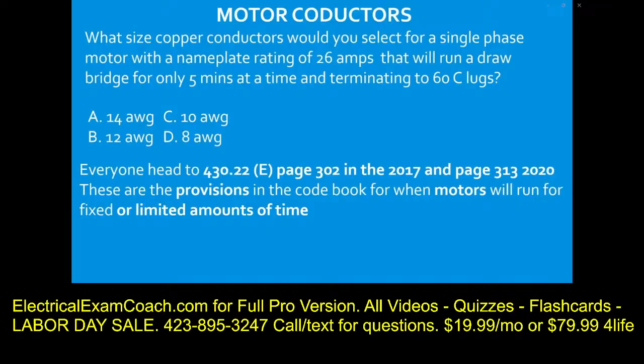Okay, so now we are going to go to Table 430.22(E). It's usually on the next page of your code book. So whether you're in the 2017 or the 2020, it's typically on the next page over. When we get to Table 430.22(E), let's look at it now, starting with the black bold heading. It says duty cycle service. Pretty sweet.